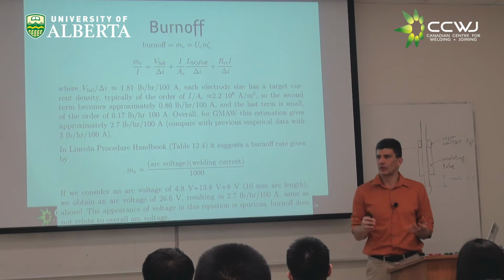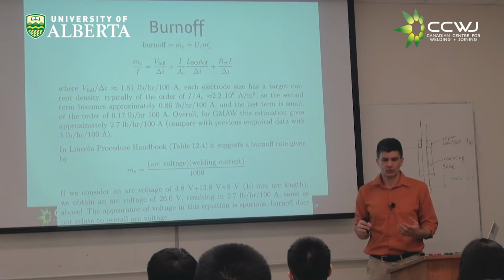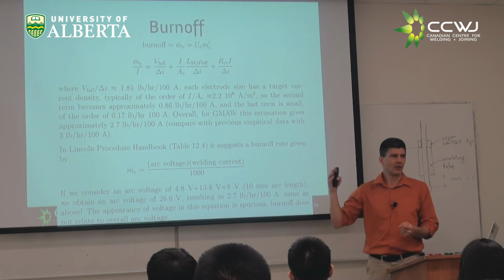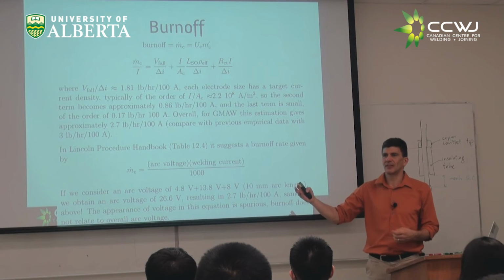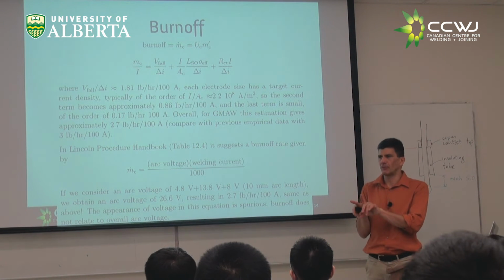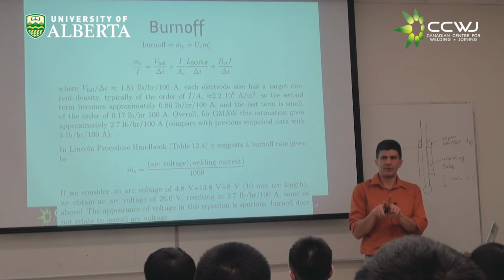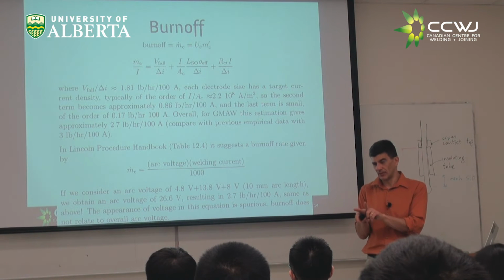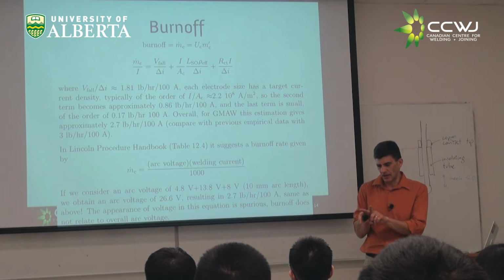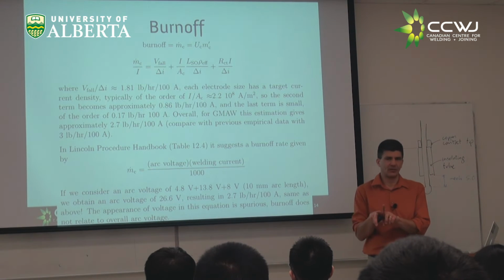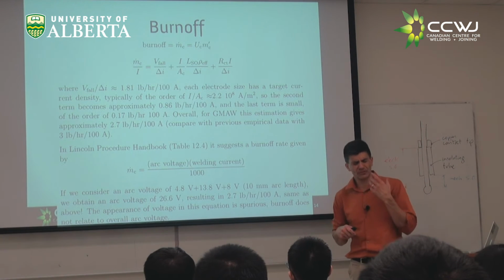That is fantastic, because if you have to do a certain job, now you know how long it's going to take you. If you know what groove you need to fill, you know how many pounds you need, and then you know how many hours you need, or how many amps you need. You start knowing so many things.